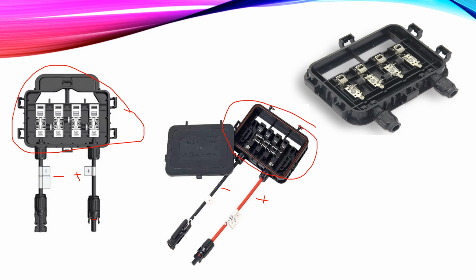Now I would like to connect these two panels together in parallel, not in series. If I would like to connect them in parallel, then the positive should be connected with the positive, and the negative with the negative, right? Because we are connecting them in parallel.